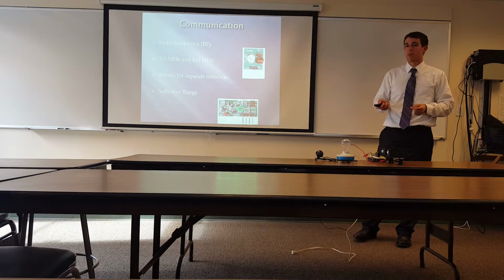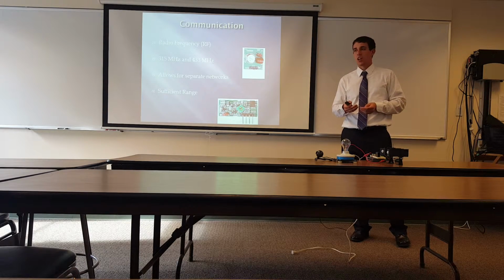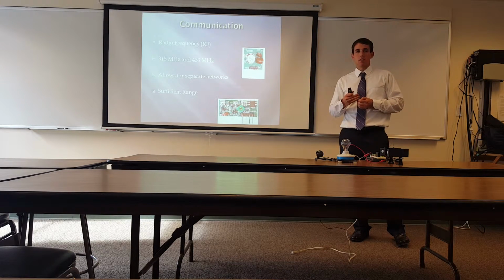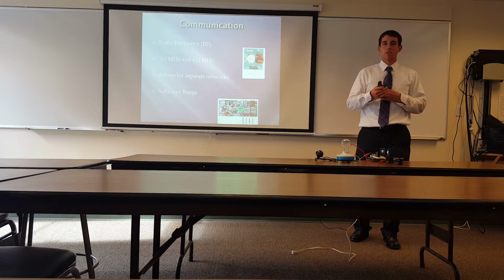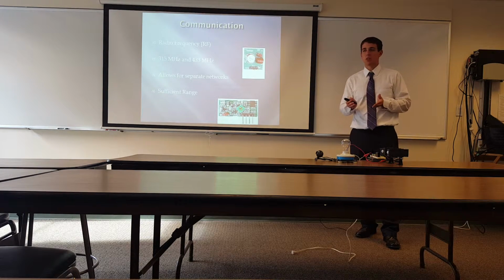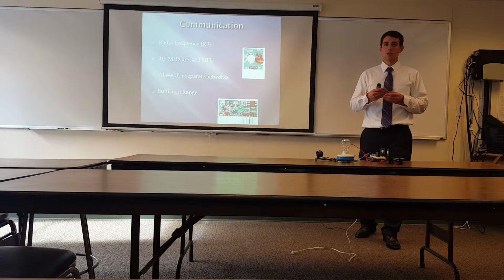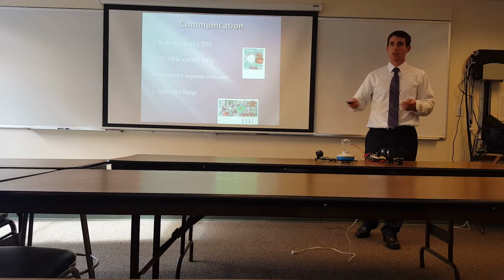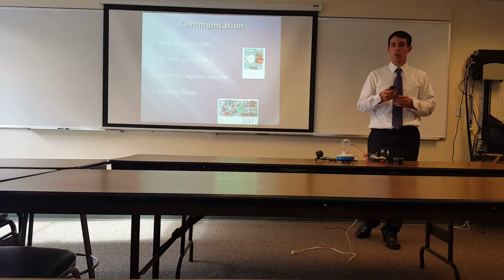I also picked the RF modules because they have sufficient range. In open view, they have a transmission range of about 500 feet, which correlates down to about 100 feet indoors. But I've used this around my house from one corner to the other, and they work fine with no problems.